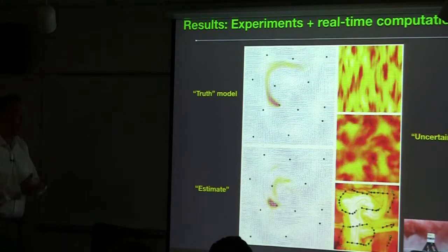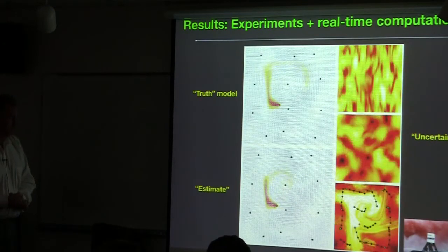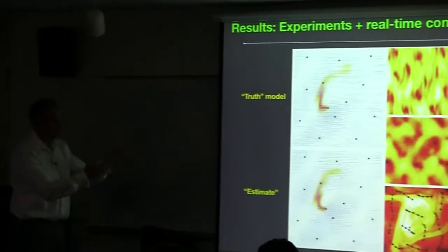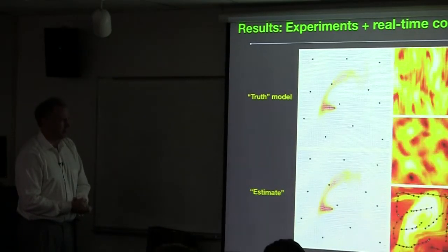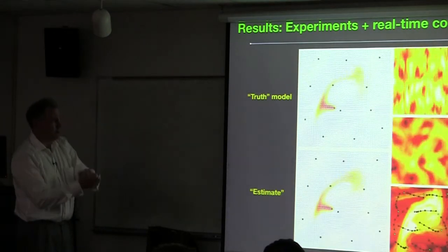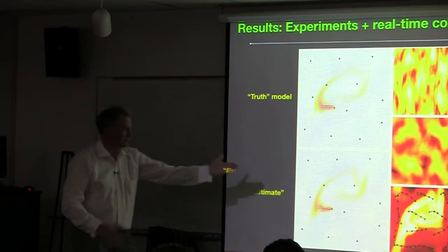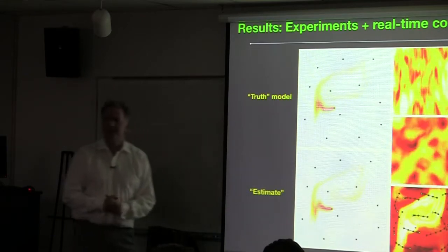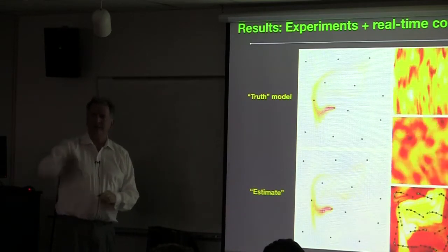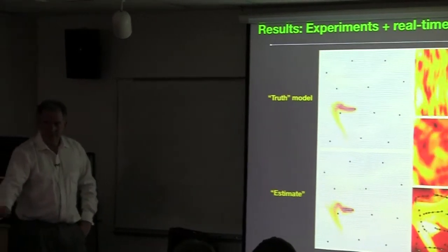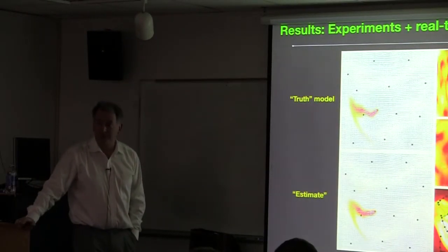So it's a standard receding horizon model predictive control framework, but applied to minimize the cost function, which is the trace of the covariance matrix at the forecast time, where the covariance matrix is a function of the C matrix, and the C matrix is a function of the position of the sensor vehicles between now and the forecast time. Yes? So you said that the C matrix doesn't depend upon the measurements. C does not depend upon Y, right.